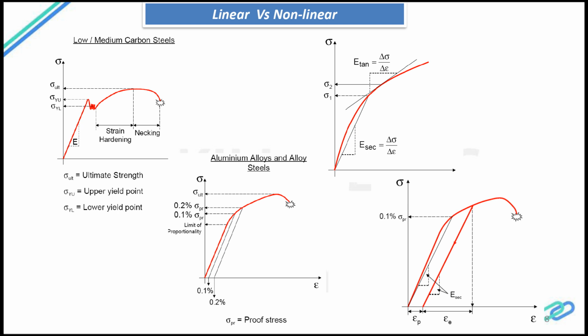And over here you can see a normal stress strain curve, which is something similar to the aluminum alloy, where it exhibits the linear and the nonlinear regions. When it reaches the 0.2 percentage proof stress and when it unloads, it comes down and sits as a permanent set of the plastic strain.